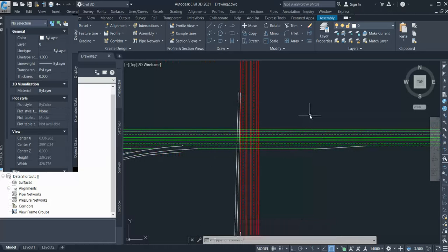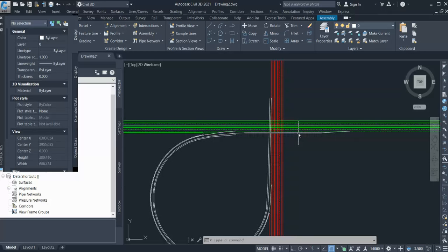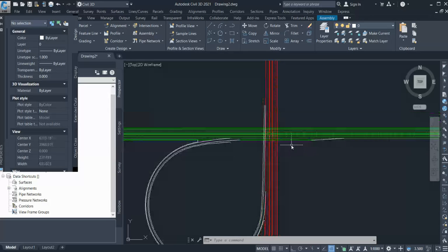So, yep, this is the loop design or any slip road design, how you can divert your roads, what would be your cross section for the slip road. In case you have a double lane, 2 lane slip road, it should be double the value. So right now for single lane it is around 150. For 2 lane you have to provide auxiliary lane plus again the divergent taper. So when you have a 2 lane you have to provide double length, and in some cases the fork type of arrangement is also done.